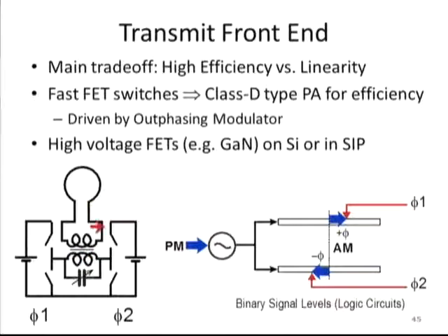This would be highly efficient, and if the phases of these switches are driven by a simple outphasing scheme which could be implemented all in the digital domain, where phase modulation is imposed on an oscillator, and then taps are taken off delay lines in an advanced and retarded phase like this, we can exactly reconstruct any modulation.